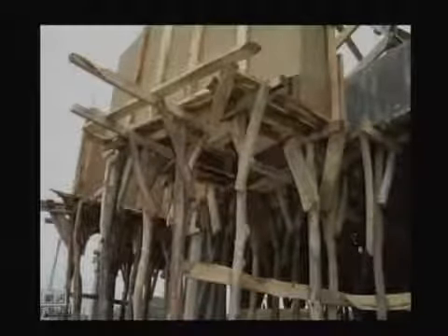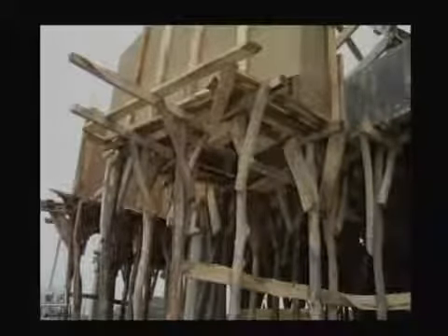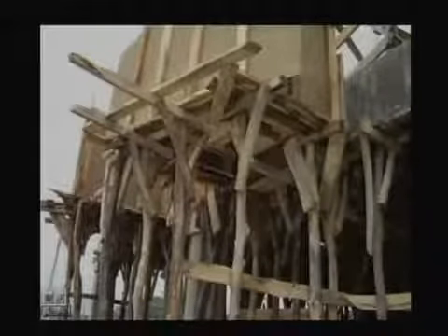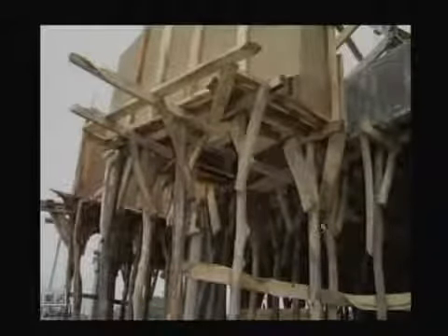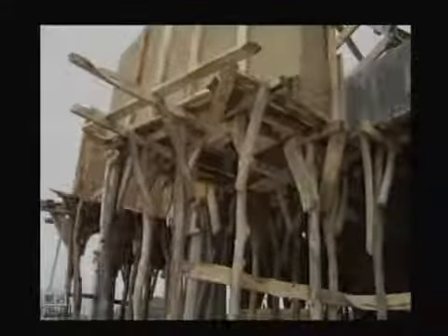Fresh concrete, green concrete, does not have any strength, so it will simply fall down. So you have to use these supports to withstand that load, and only after 28 days, or maybe after 14 days, will you get the required strength. Generally you take the supports out after 28 days, and then you can see that the structure that is built can take the load for which it is designed.